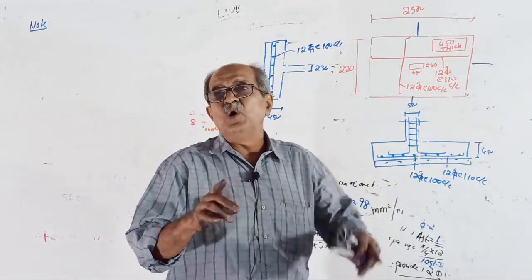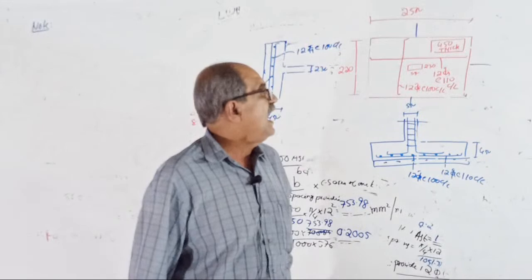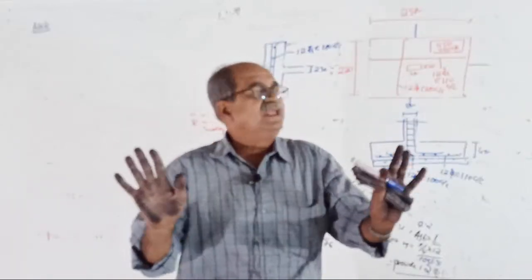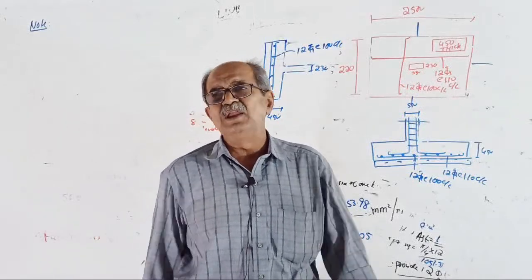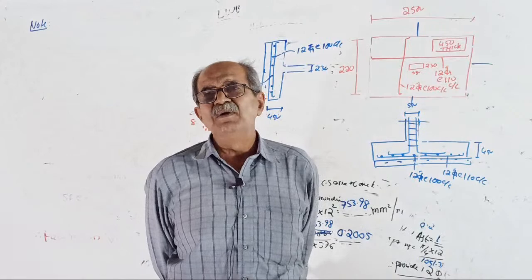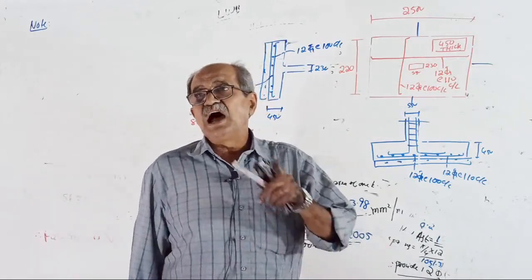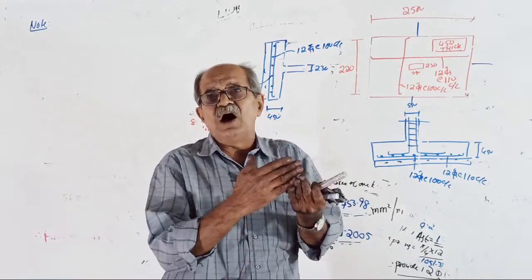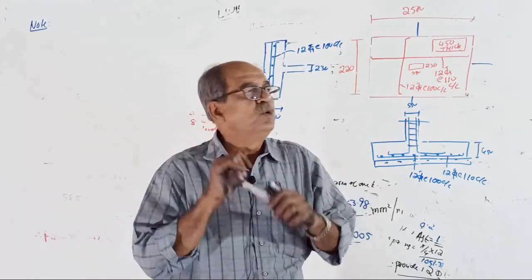Then, what you do is, what I told just now. Thickness changing, you go to property page, change the thickness, done, over. And check for punching shear, you don't have to worry. Why? ETABS and SAFE will take care. Or I will tell you in top, ETABS and SAFE, I will tell software will take care, over. Now, check for our wide beam shear or shear causing diagonal tension. That check you have to do.